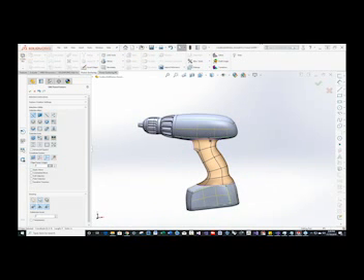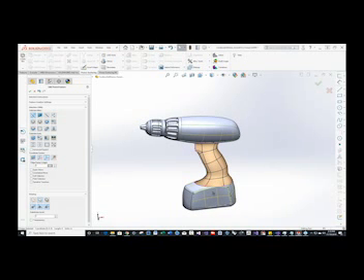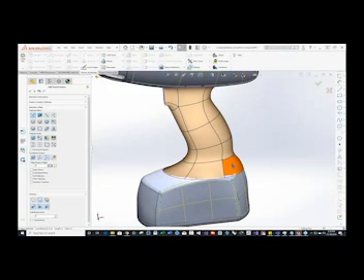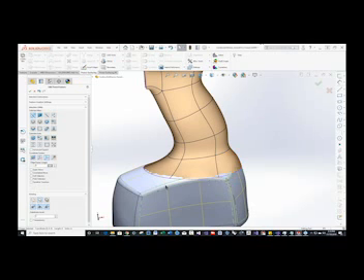And we have imported some surfaces from the other SubD on the top, and we've imported some surfaces down here. Now, the cool thing is that because this is all filleted and tangent, I don't need to have an edge break in here. So you can see that this edge kind of flows over that fillet.